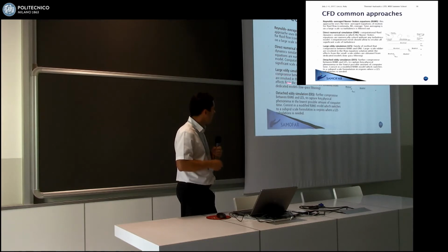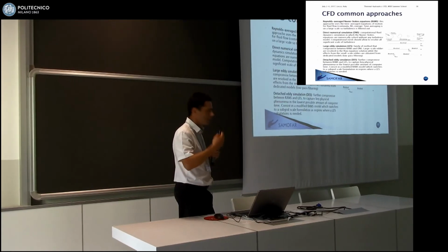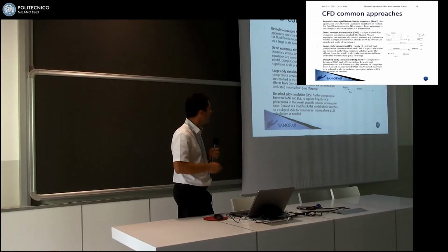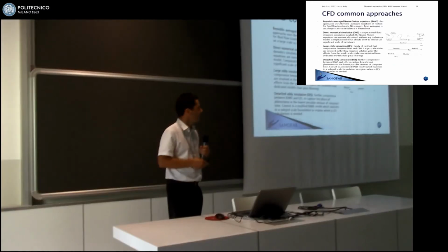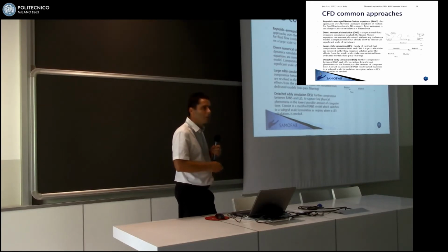Then you have another family of methods, the LES, large eddy simulation, that will put a filter in the resolution of the Navier-Stokes equation. They will consider some vortex up to some size, and then the rest of them they will just model by a closure equation. And then you have, I would say, the more exact method, the direct numerical simulation, DNS method, that basically makes no assumptions in theory, and will resolve all vortex of all sizes.